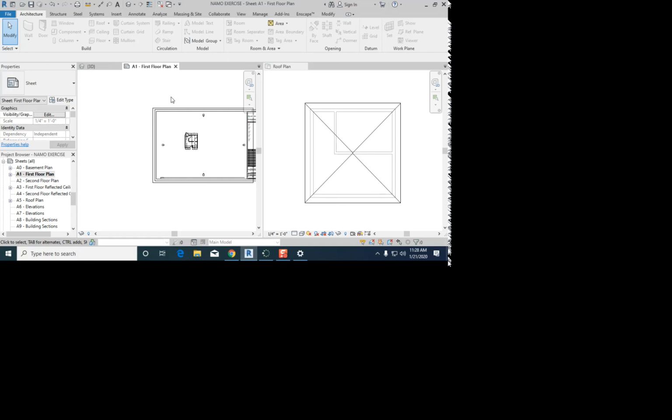When you guys are working on a door or even a window, what's a keyboard shortcut to quickly flip them around? Good. Spacebar. Spacebar just kind of flips things around. And again, on your screen, it's those double-sided arrows that are kind of opposite from one another. So you can use those to change the face of things or the hinge of things.